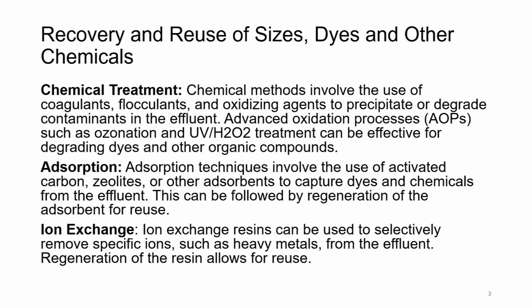Adsorption. The adsorption technique involves the use of activated carbon, zeolite and other adsorbents to capture dyes and chemicals from the effluent. This can be followed by regeneration of the adsorbent for reuse.